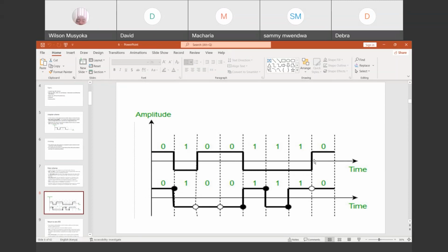But like you can see, it is going to be affected by baseline wandering and a synchronization challenge, compared to the other one, whereby you have an inversion: a one will go down, and then you operate at the lower level until you find another switch for a one.